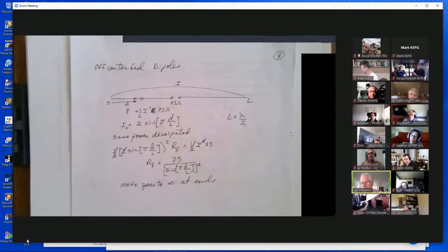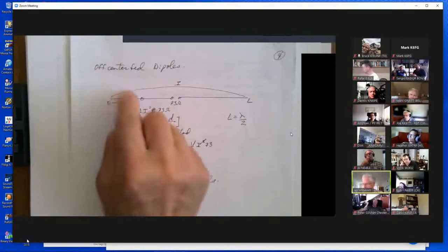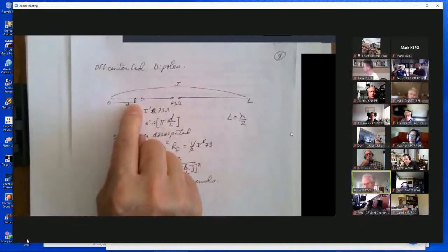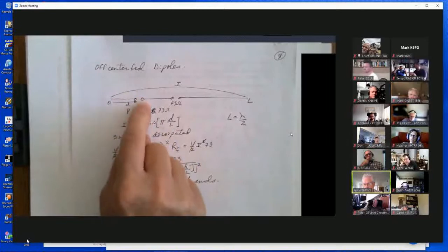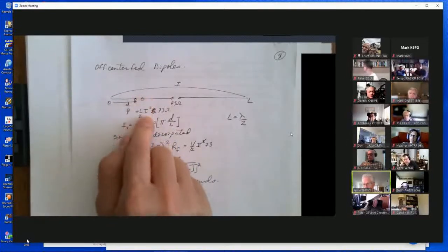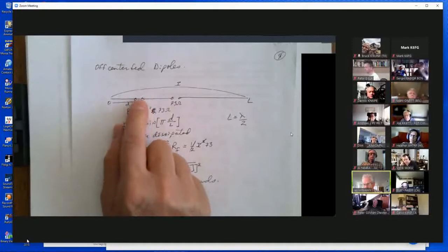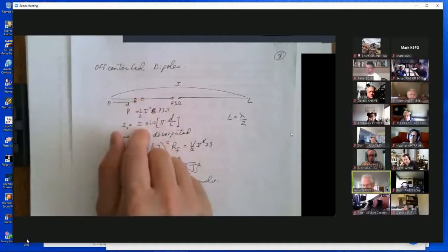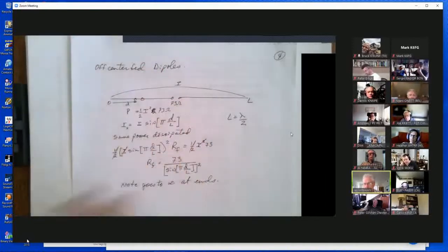Also, one other thing you have to watch out for is this is somewhat unbalanced. And so you may get slight differences in currents, which causes a common current on your ladder line. Typically, you'll want to feed that with a balun to make sure that you don't get currents coming back and burning the noses off your operators or their fingers on the key. Okay.